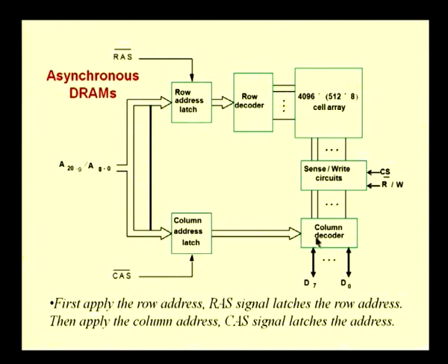Now, this you can see goes to the column decoder. The column decoder now will decode and select the correct column, and we will get the data here as your data lines. Okay. So, D0 to D7, if there are 8 planes here, from each plane you may get one data line that is being selected.